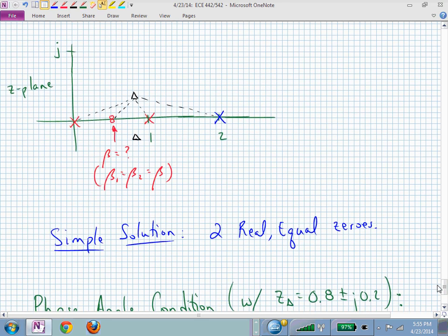The red poles and zeros correspond to our controller poles and zeros, and if we say PID, we immediately fix a pole at 1 and another pole at the origin. And what we have available to us are those zero locations.